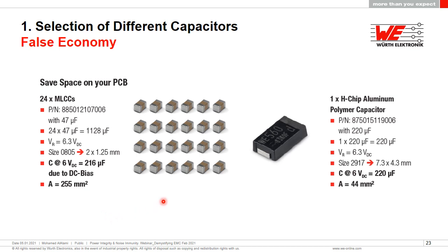There is still a place for polymers. I'm absolutely convinced that they are the better technology. Sometimes it's just about the cost, but for me that's false economy, because you are using more area. And given the issues that we've had with sourcing MLCCs just a couple of years ago, where everything was on allocation and you couldn't get them, they were like gold dust, I think it would make sense to combine. I wouldn't say just use one technology.